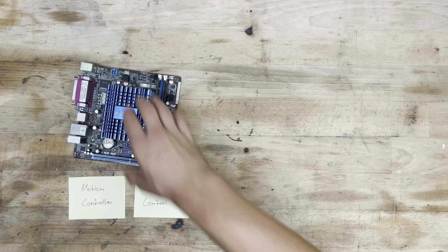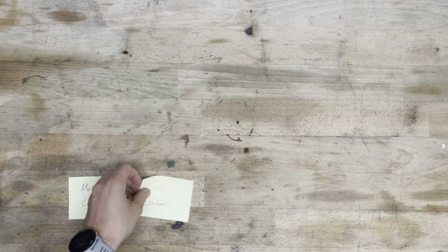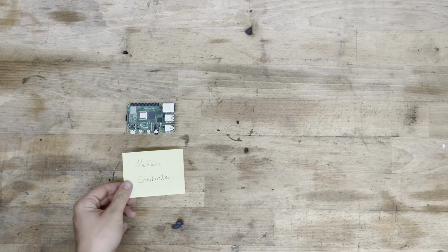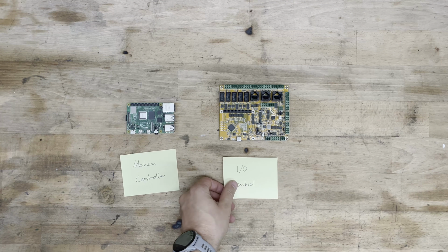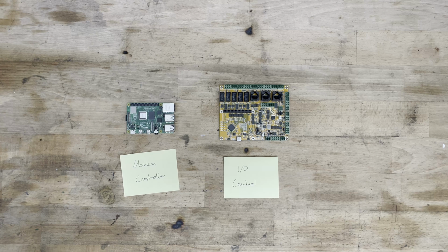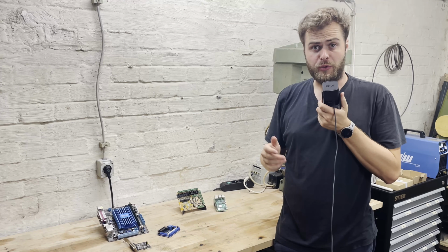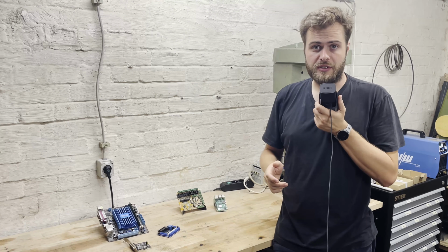Moving to more advanced systems, the task of interpreting G-code and generating pulses for the motor driver is split up between two components. One part handles the general machine management, and the other deals with the I/O manipulation. By splitting the tasks, we eliminate the need for a legacy parallel port. Instead, digital communication protocols like SPI, Ethernet, or EtherCAT are used. These boards here are just examples. I recommend checking out the LinuxCNC documentation for a full list of supported boards. The more modern approach also removes the inherent I/O limitations of the parallel port and allows us to use much more advanced inputs like encoders for precise feedback next to the basic ones such as limit switches.